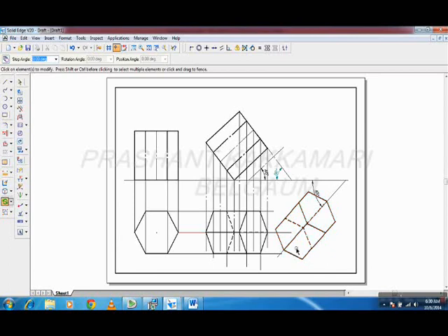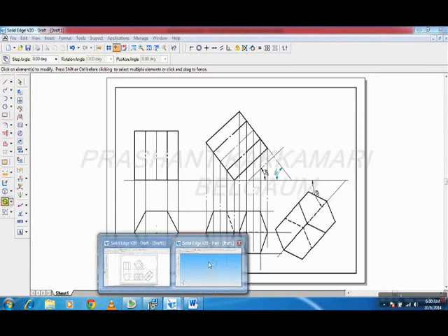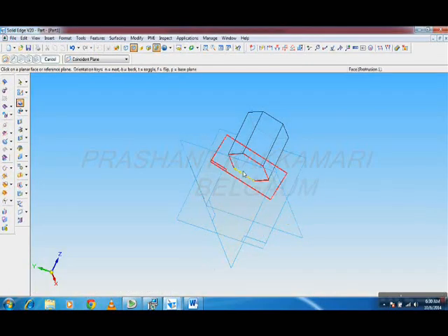Now if you see from the front view, I am going to observe like this. The bottom face is visible, top base is not visible, then all lateral edges or the surfaces you can observe. This surface is visible, this surface is visible, this surface is visible. What about this? So some of the lateral surfaces you can observe, those are invisible. So connecting those edges you have to draw it hidden lines. So that can be drawn only by assuming or imagining these things.